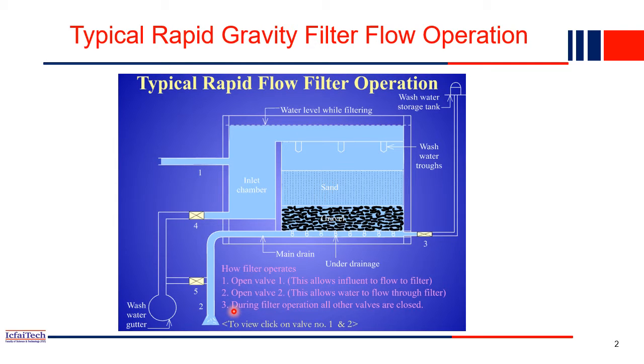Now, in the last lecture we discussed the backwash of the rapid sand filter, because after one week or so of filtration, the impurities will fill the pores in the sand bed. So we have to clean the sand bed repeatedly, every day or every week, or on alternate days. How are we cleaning it? We use the backwash of water.